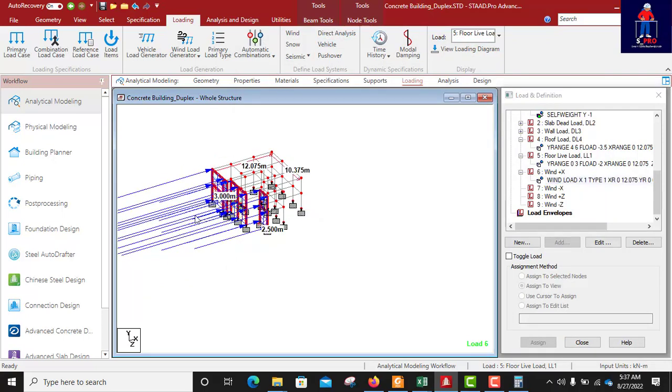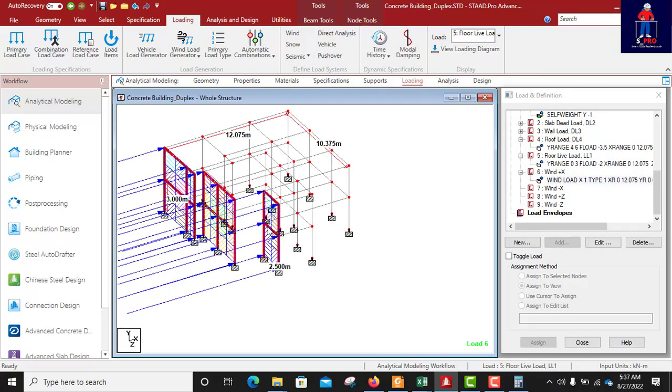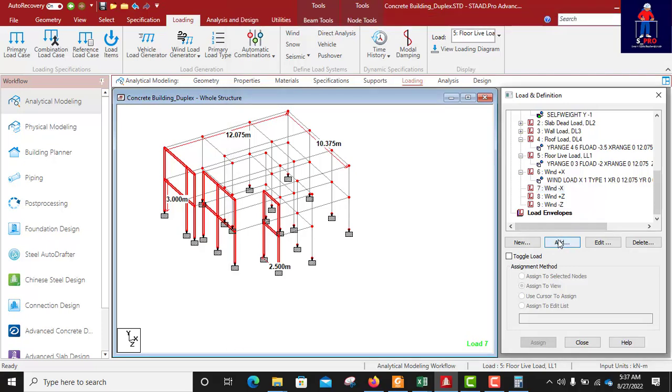This is how the wind is going to attack the building from this side. Yes, it's not an open structure. If I had checked that box as open structure, you see this wind affecting the internal columns, which is not going to be so. The blocks will not allow wind to pass through and affect the internal columns. But the elevated water tank we did is an example of an open structure. It is open. So the wind that is affecting the first column will definitely affect the second one.